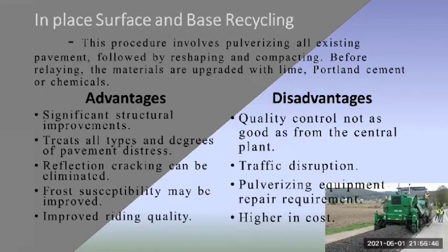In-place surface and base recycling. This procedure involves pulverizing all existing pavements, followed by reshaping and compacting. Before relaying, the materials are upgraded with lime, Portland cement, or chemicals.